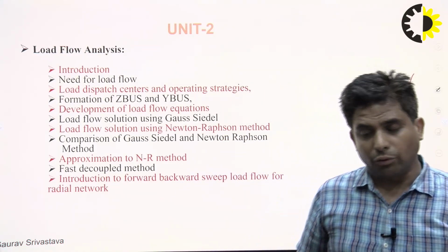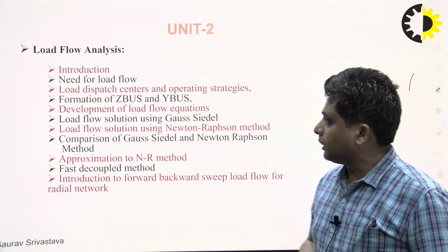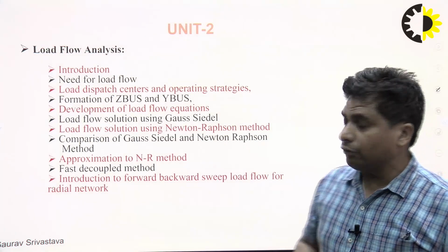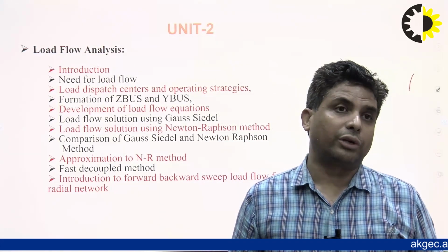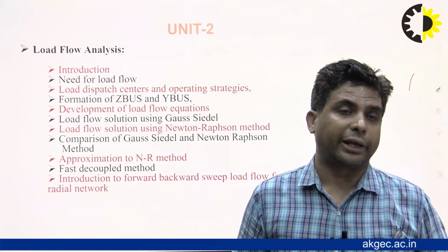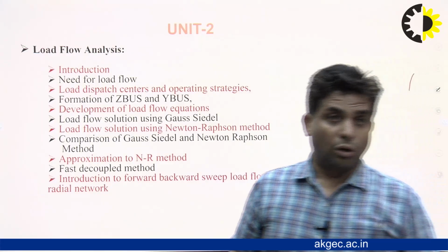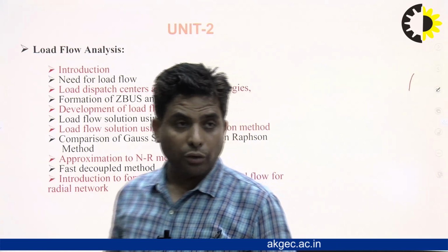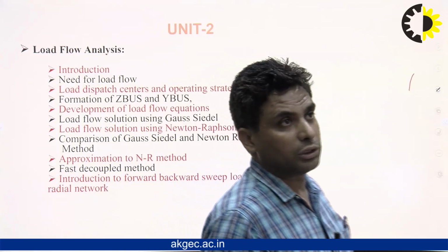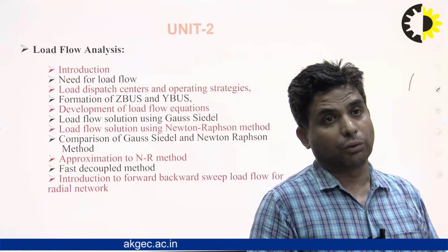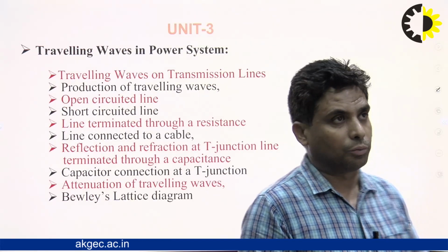Then the formation of the Y bus and Z bus, and then we develop the load flow equations, like the active power and the reactive power, and how they can be controlled. For the next generation point of view, or for future planning, we have more discussion about how we can control the power generation and the power requirement from the power flow point of view.